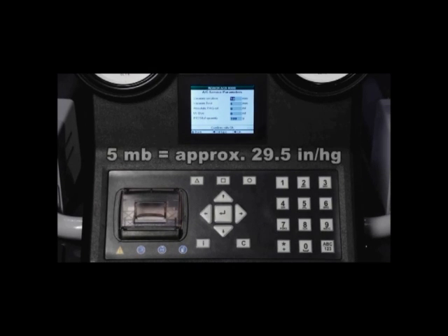Now, when I run the vacuum pump for 10 minutes, before that timer starts, this machine must pull down to 5 millibars. My timer does not start until I get down to 5 millibars. It could take from 8 to 10 minutes. A good way to help you make that service faster is have the vehicle to operating temperature. Once I've created my vacuum time, I will also do a vacuum test time, which will be 4 minutes. And then I will do my absolute oil, or my dye, or my refrigerant.